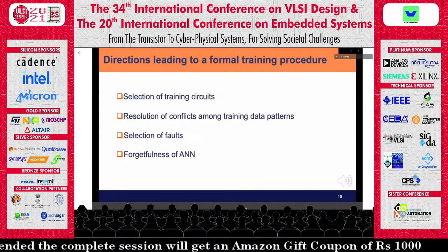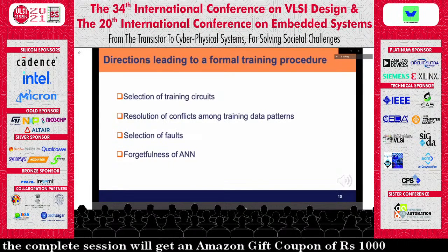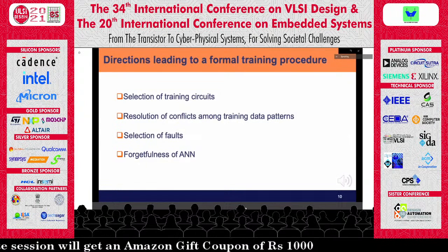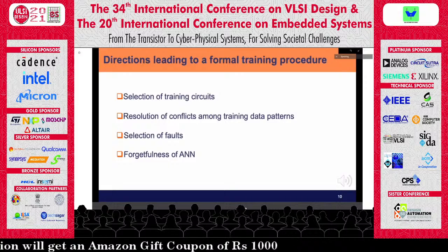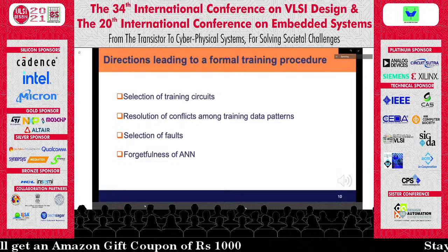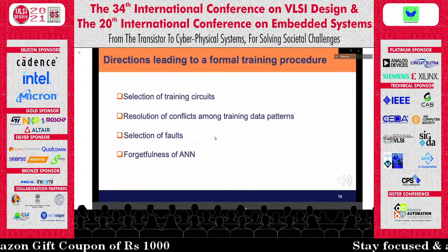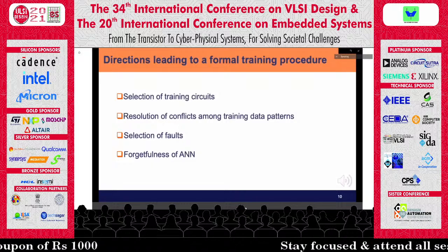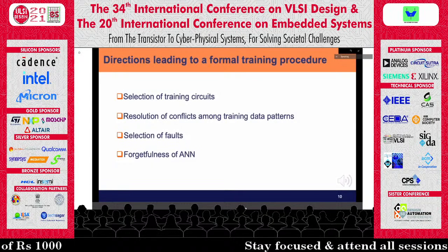The upcoming slides give a novel method of training the ANN considering three aspects. That is, the training error of the ANN must be kept low by adjusting the number of hidden neurons. Training data from a fault must be accepted only if guidance from the resulting ANN reduces backtracks, and the faults used for training data generation should not be restricted to hard-to-detect faults. In fact, a fault provides useful training data as long as it reduces backtracks.